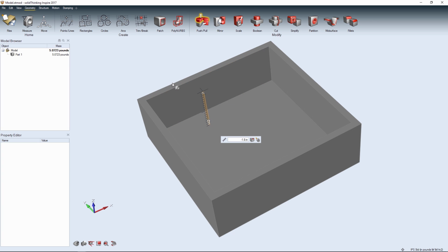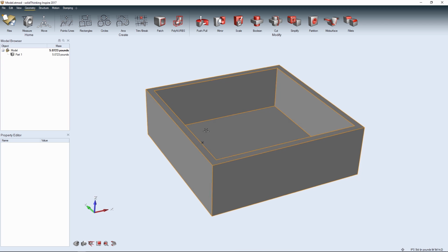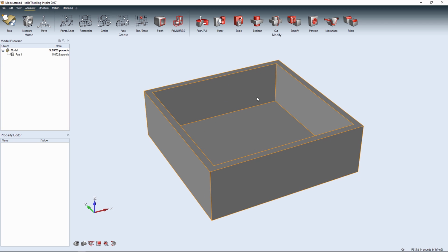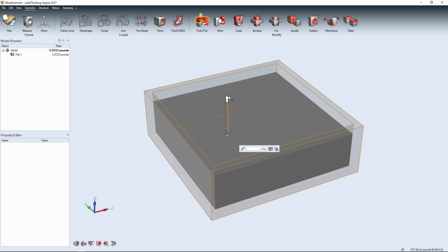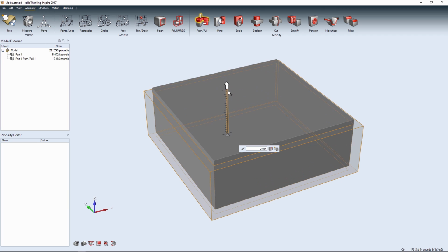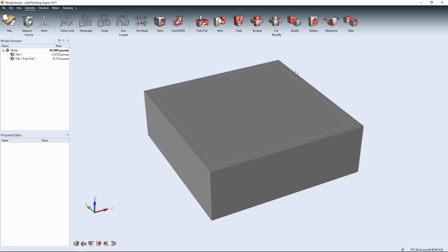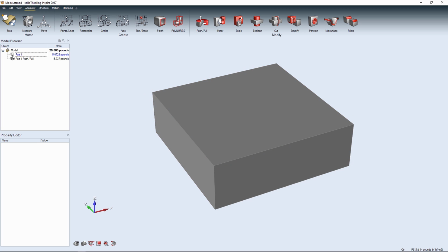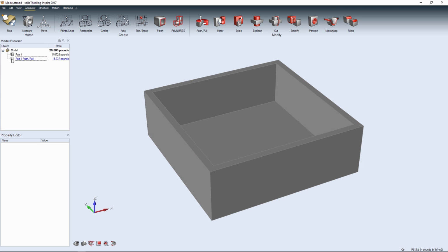So I just created an empty box. If I wanted to create a box or a design space to optimize within this, I can click on a face, hold Shift, and pull up off that face. Now I'm creating a second body off that existing face. So I now have two bodies. And over here on the left-hand side, I can see the different bodies in my model. There's the inside body, and there's the outside body.